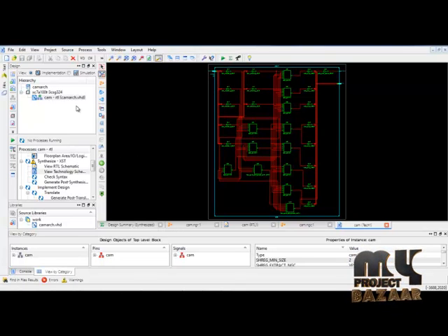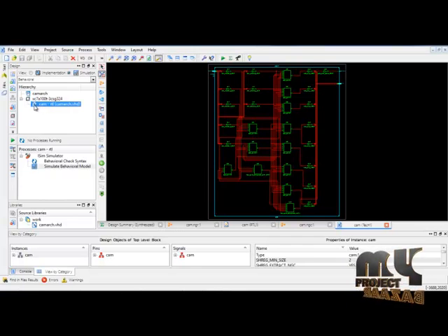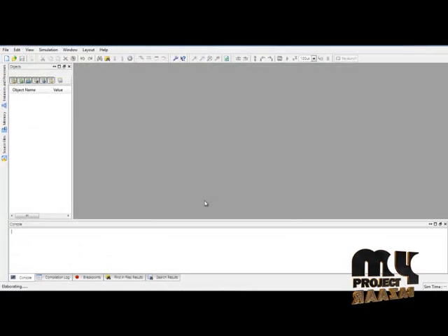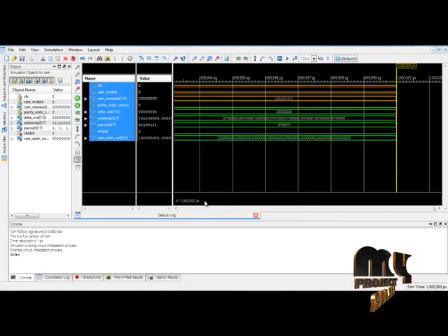Then, we can view the timing diagrams of the output by selecting the simulation option and selecting our main code. Then click simulate behavioral model. This provides the timing diagrams for the logical design. In this case, it will create a GUI. Here I am using ISim for visualizing our outputs.